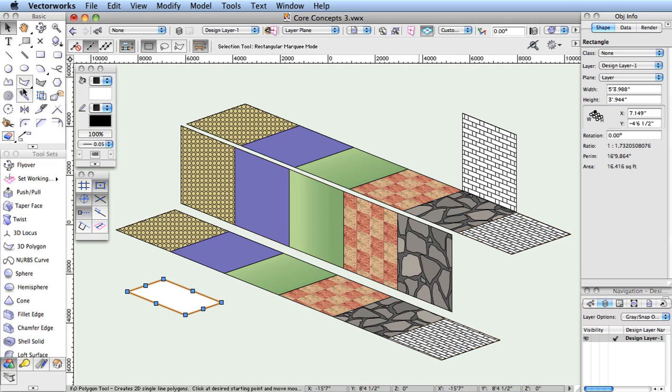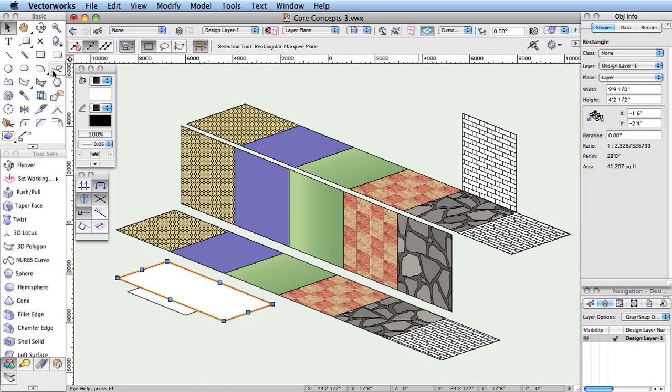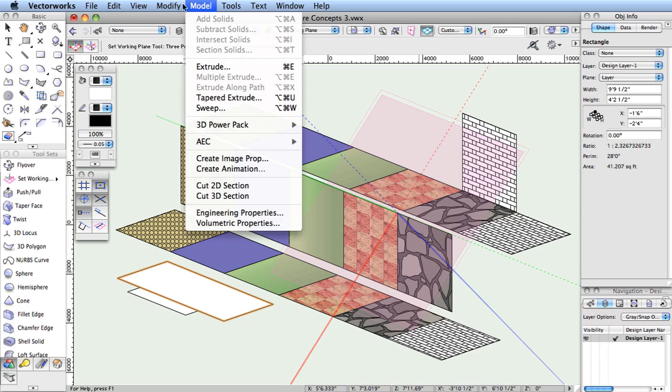As you're working in Vectorworks, you may want an object to respond to a working plane that is not horizontal or defined by any other saved planes. For example, you may want to align solar panels to a sloped roof. In this case, you can define a working plane that is parallel to the roof face, and when it is active, all creation, editing, and movement is observed relative to the active working plane. Once it has been defined, it can be saved and reused later.